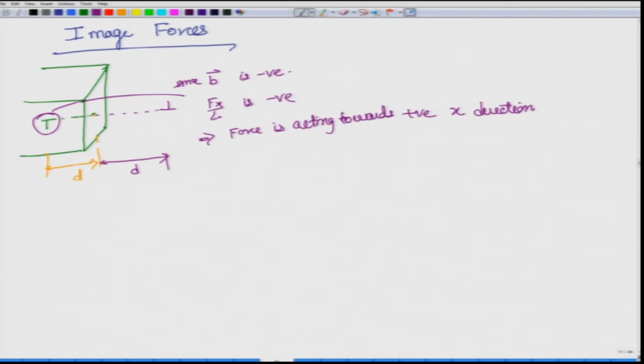So, the net effect is that this dislocation is forced or tries to move towards the surface, and this phenomenon is called the image force, because you can see why it is image: there is no real dislocation over here, but there is still some force acting onto it, probably some kind of ability of the material to decrease its energy by annealing out the dislocations.